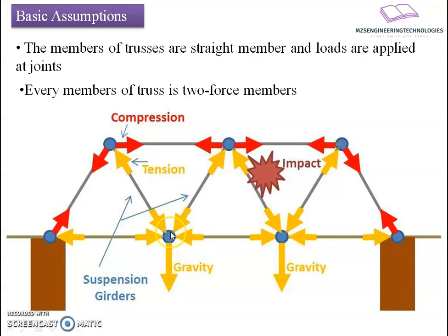If, instead of this, I say the load is applied on this end, what will happen? This end will now get stretched, and suppose the load is applied in the horizontal direction, likewise this will now stretch, and the members which were in compression in the initial case will now act as tensile members, so they will be subjected to a tension pull here. There will be a pull and push action, and a reversal of this pull and push action within the members. That's why a truss member is said to be a dual action member, and we say that the end connections are pin connections.